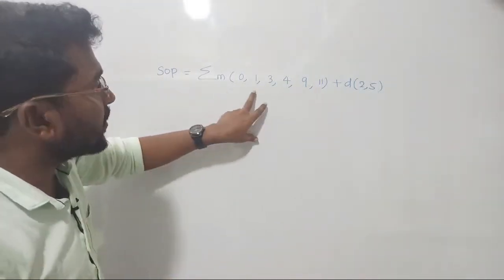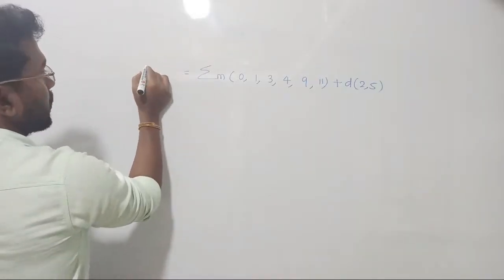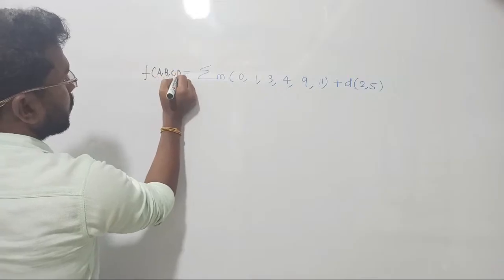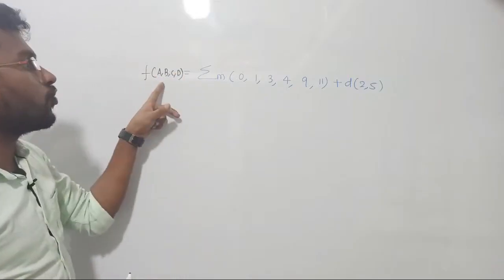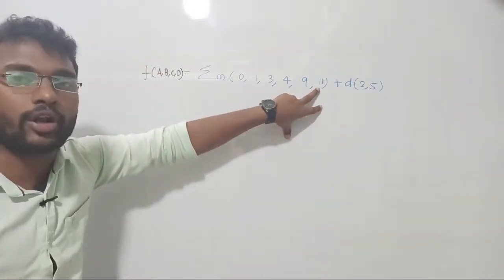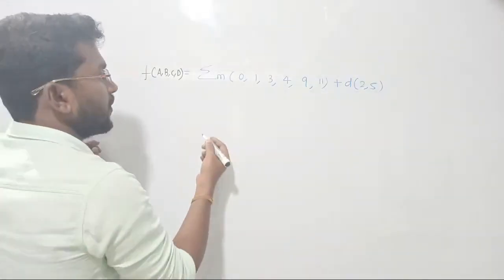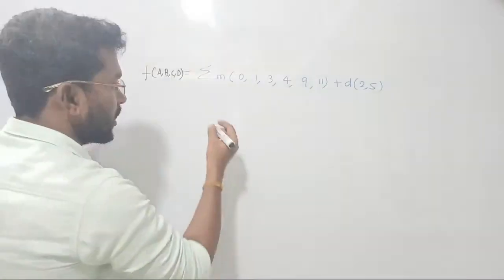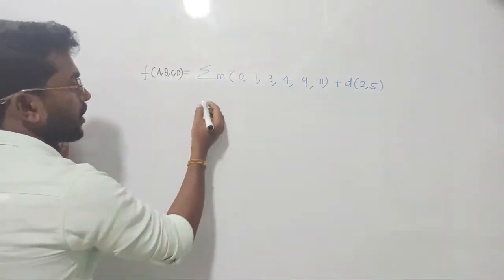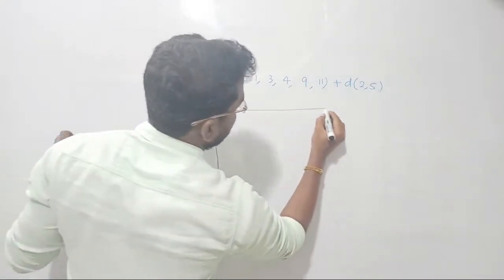See there, these variables are going up to 11, right? They will give you the function in the bracket, representing how many variables they have considered. Given it is 4 variables, if you see 9, 11, then automatically it is 16 cells, right? Since it is given in sum of product form, we have to consider sum of product. For that I have to consider 16 cells.